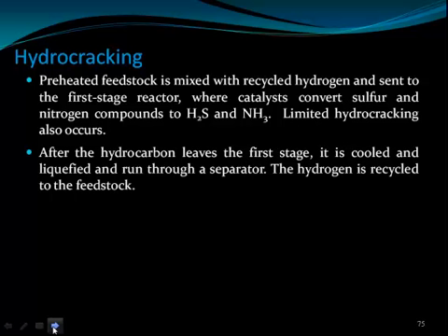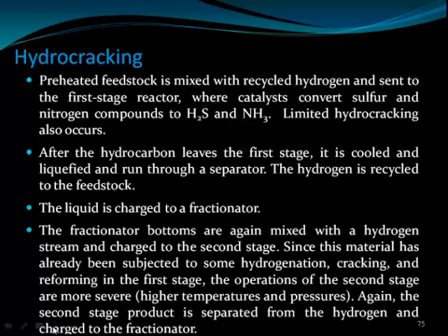After the hydrocarbon leaves the first stage, it is cooled and liquefied and run through a separator. The hydrogen is recycled to the feedstock. The liquid is charged to a fractionator. The fractionator bottoms are again mixed with the hydrogen stream and charged to the second stage.